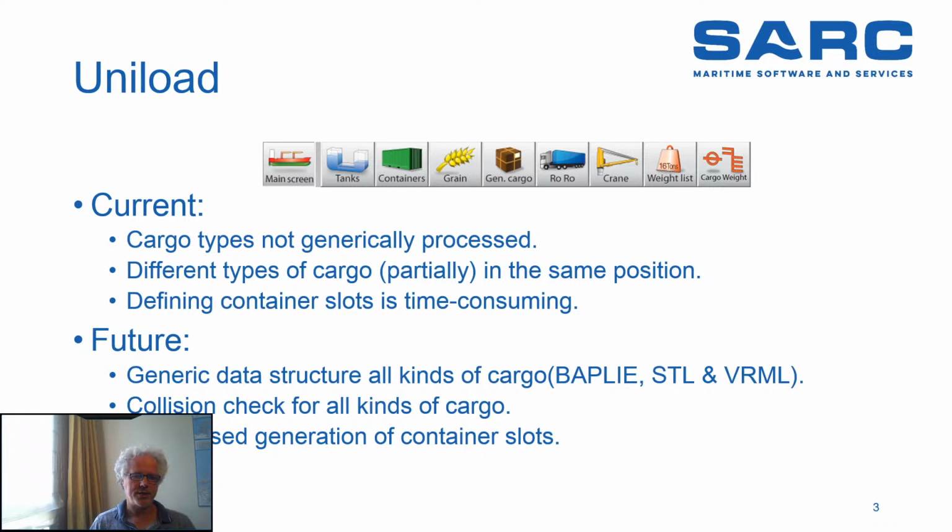For PIAS and LOCOPIAS, and particularly for LOCOPIAS, we have created quite a few modules to define cargo with. And we started that in the DOS age, and that has grown and grown and grown. And basically we defined a new module for every different type of cargo. We are now in a place where we can actually integrate all of them, and we will. So we are now working on a shared storage of all types of cargo, and that means that it's easier to draw them and that we can do a clash control between containers and general cargo, that we can pick up a container in the crane module, etc.